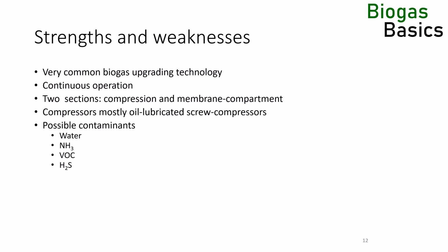H2S is a known impurity of biogas. While it will not necessarily damage the membrane, it will break through into the biomethane and can cause gas quality issues shutting down the upgrader. Typically, H2S is removed with an activated carbon filter.